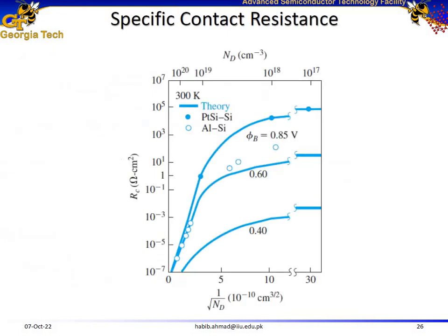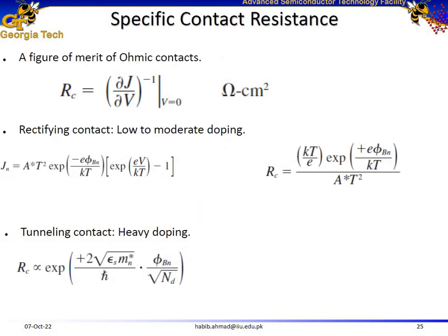And then specific contact resistance. Specific contact resistance is a figure of merit for contacts to devices. For example, if you have manufactured a p-n junction diode, you need to make contacts to it. But if your contacts are Schottky, you don't know if the diode behavior is coming from the p-n junction, or from the metal-to-semiconductor contacts, or if it is a compound effect of the two.